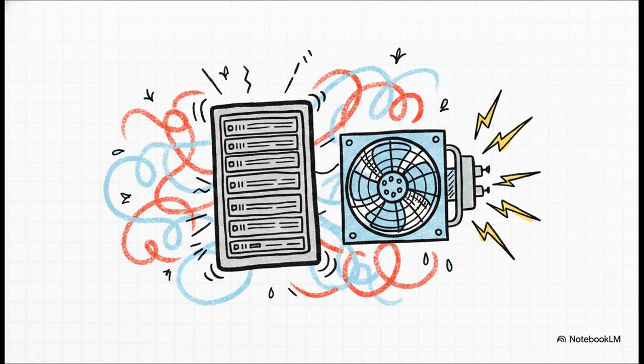So here are the consequences of mixed air. Higher energy consumption, reduced cooling efficiency, dangerous hotspots that actually damage equipment, and increased strain on cooling units. The crucial point here is what happens if that hot exhaust air casually mixes with the incoming cold air. It triggers a catastrophic domino effect. The cooling system suddenly has to work so much harder to maintain safe temperatures. This mixing directly leads to all those nasty consequences we just mentioned. It puts an incredible strain on the whole operation. The goal, then, is incredibly simple in theory. Separate the hot air from the cold air as much as humanly possible.